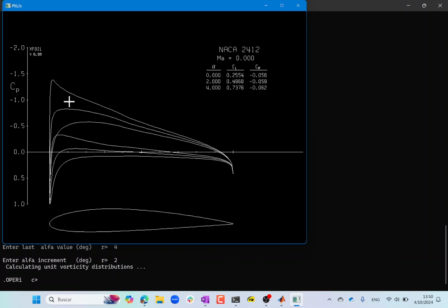No, you can put a negative camber. So the camber is always going to be positive, but you can just flip it around, right? If you ask a positive camber airfoil to generate negative lift, it's the same as just flying backwards. So you're going to be doing something, just NACA double top, right? And if you go to operating condition, just set the alpha, the angle of attack, let's see, minus one. What do you get? How big of a negative angle? Negative 50.